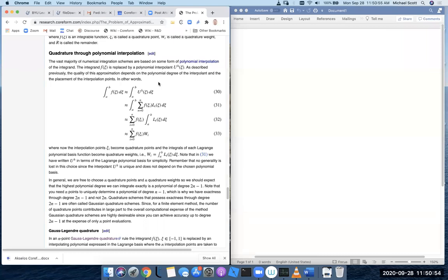But then if you do reduced quadrature on the same problem, locking goes down. So it is like mapping to a different interpolation space. Yeah, that's exactly right. You can always overcome these problems by just refining the heck out of the problem. But the point is you're just kind of kicking the can down the road in that case. You're not actually solving the problem.